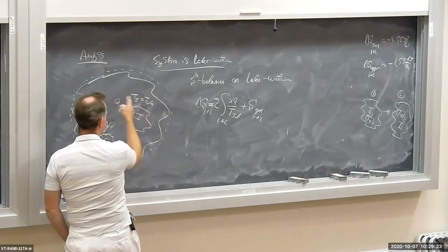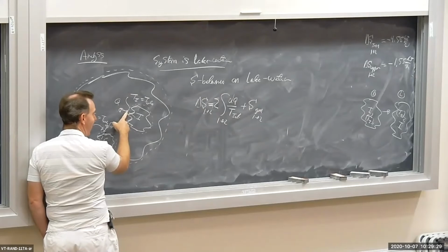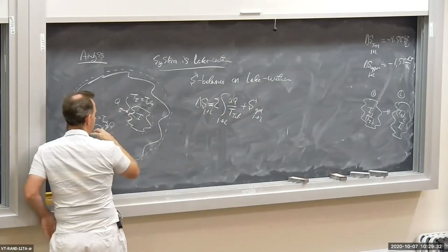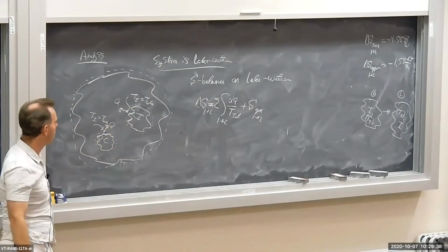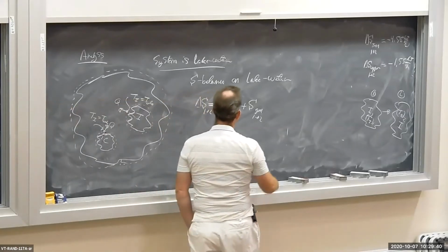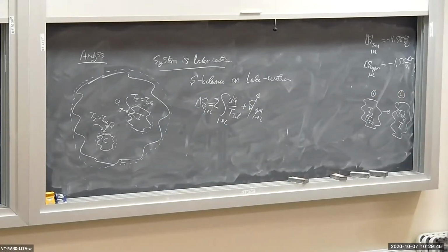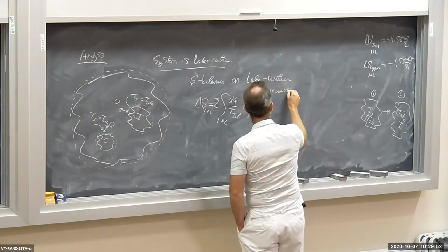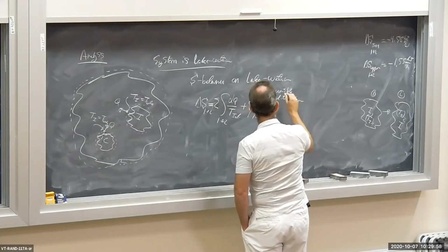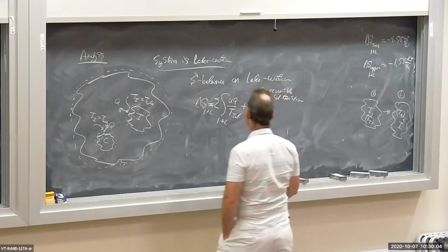So this implies reversible heat transfer. The heat enters the lake water system at the lake temperature and then disperses throughout the lake. So there's no temperature change as that heat gets dispersed throughout the lake. So that means reversible heat transfer, there's no entropy generation. Okay, so that term goes to 0. So all I got is this integral, del Q over T.